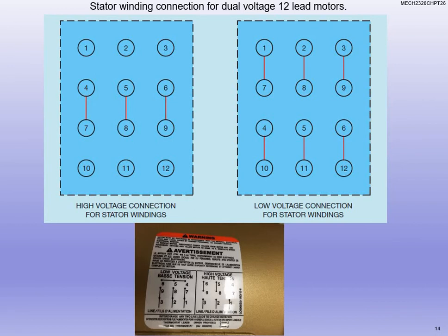It might be on the outside of the motor, or it might be on the inside of the plate, and it's going to be something like clear coated so that it's protected as well. But it tells you where to wire up. When you pull your lines in, you're pulling in 1, 2, and 3. Those are the lines you're pulling in. The other connections are made so that you know if you're using delta or Y, or if you want to pull from 240 or 480 on that particular motor.